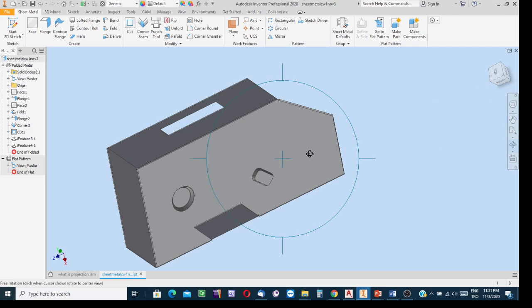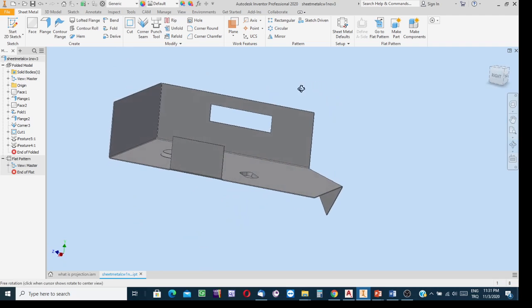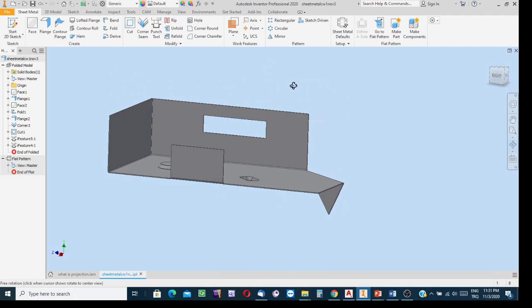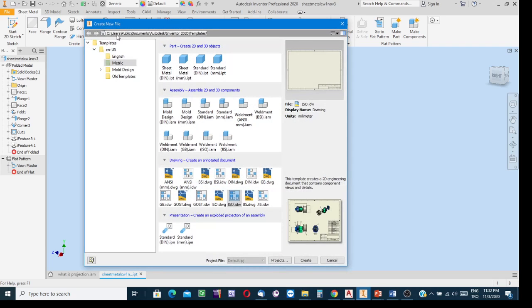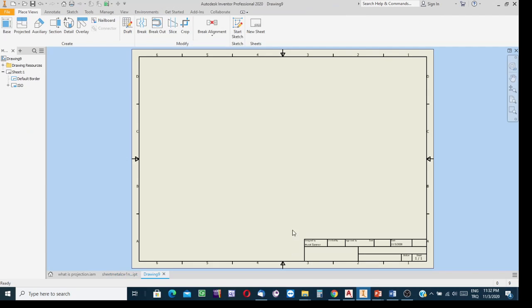Yes, say that, assume we finished the model creation part. It is a sheet metal work. Update the file, and then how about the views? For this object, let us have the necessary views. It is going to be a new file. Click on new file creation button. I selected metric quadrant. Metric option means first quadrant. And drawing template iso.idw. Click on create button.